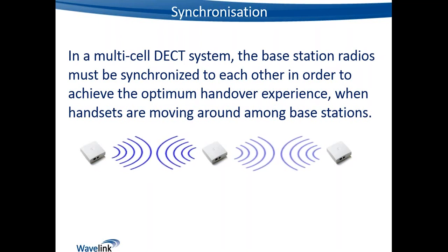So we cut back to 11 channels, and we're managing this over the air, and that's in direct comparison to digital DECT, where we've done that over the wiring in the past. So we've got a user, obviously they're talking to a base station, or they're communicating with a base station while they're on the DECT call. As they move throughout the facility, their handset will hand over between the different base stations as required.